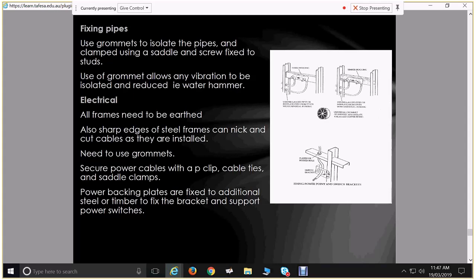So your steel framing has those holes in the middle. Still, sometimes with your steel framing, you'll get taps being located and things like that, and so the framers or plumbers on site have to introduce little bits of timber in there. They'll just use a piece of timber for doing that because they can fix in through the sides.